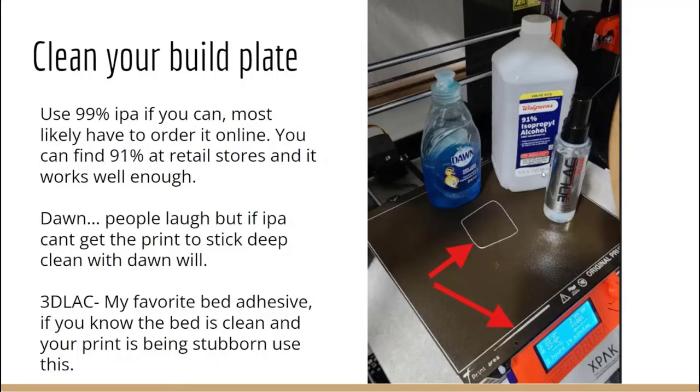But you have to be careful. It might discolor the surface. So if that's a hidden feature, unless sometimes I print things face down to get the build plate texture, if it discolors, that's not a good thing. A little sneaky trick about 3D prints: let's say you use a black filament, you have your adhesive, you pull it off, it's going to whiten the surface of the plastic. You can take a heat gun and very briefly go back and forth passes. It'll return the color back to the proper color. So that's just one little tip if anybody has ever wondered, like, hey, I pulled a print off, the color's discolored. You can use a heat gun to bring the color back.